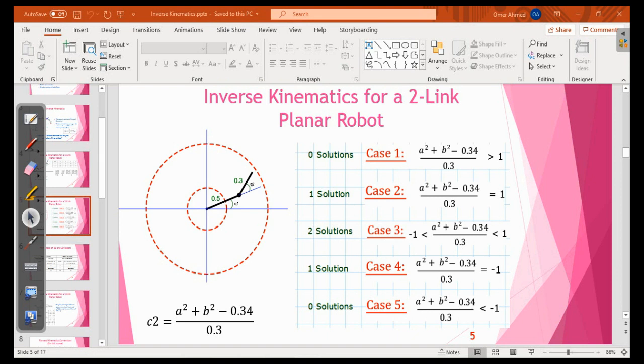Okay, in the previous video, we discussed the concept of the workspace of a robot. We saw that for a planar two-link robot, the workspace is donut-shaped. There was an outer circle, which represents the limits of the robot when it is fully extended. That is, angle Q2 is 0. Then there was this inner circle, which again represented the extents to which the end effector of the robot can reach when the second link is completely folded over the first link. That is, angle Q2 is 180 degrees.